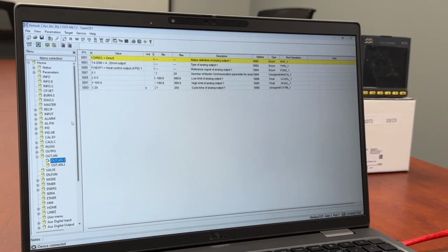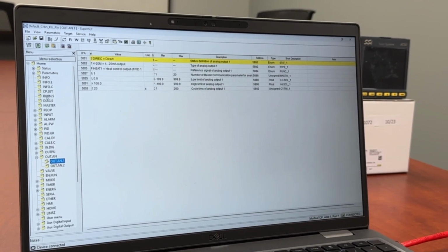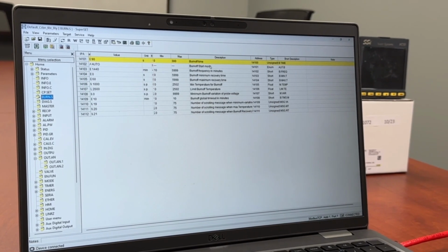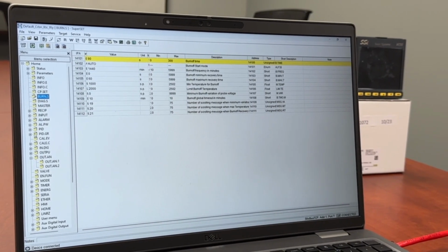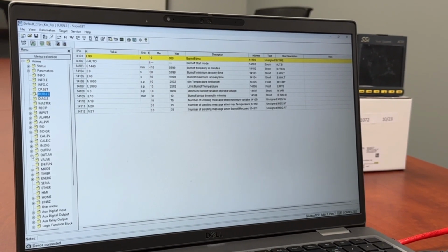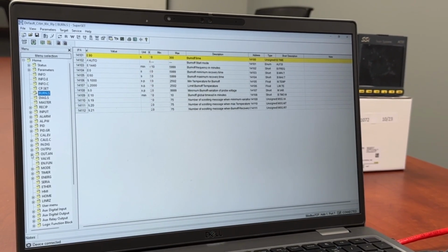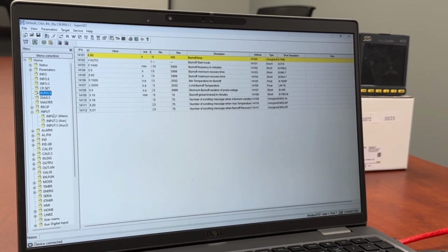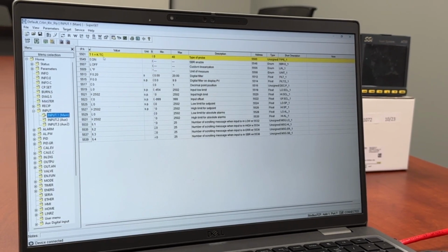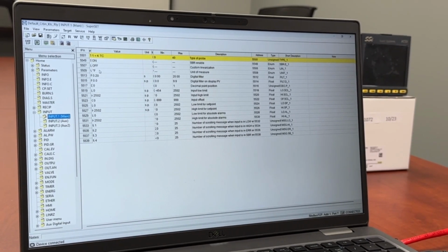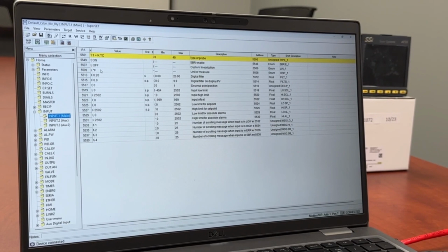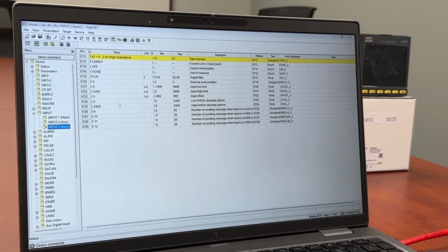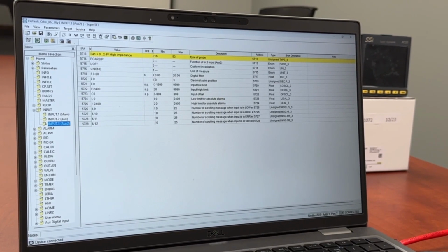You can also view settings in this parameters view regarding the burn off. We have time, start mode, frequencies. We can look at our inputs here as well. We would minimize the analog output, and then we can go to the input menu and select which input we would like. Input 1, it tells us here our TC type, also our unit of measurement, whether in Fahrenheit or Celsius, and the probe millivolt input, 0 to 2.4 volt high impedance.